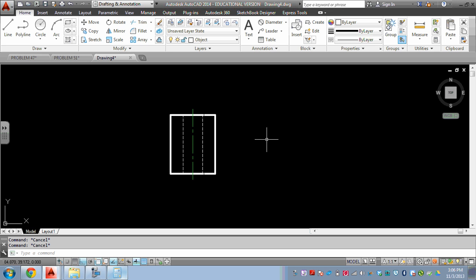So now we've got to put this tab in here. To do that tab, I'm looking and it says 1 from the top. So I'm doing an offset of 1. Select it and go down with it. And then it says the same thing from the bottom. So now I have that. It says it's 1.75 from the edge, from over here to the center. So what you can do is select this offset and do 1.75. Select the center line and offset this way.